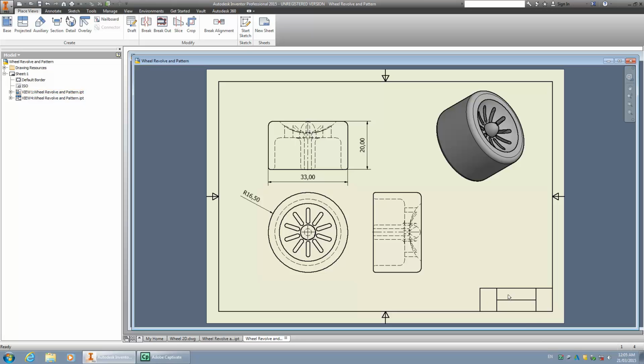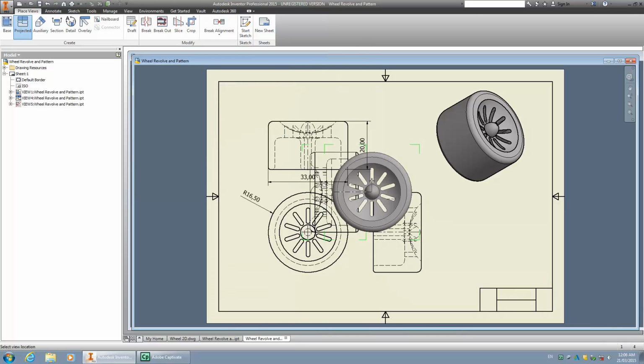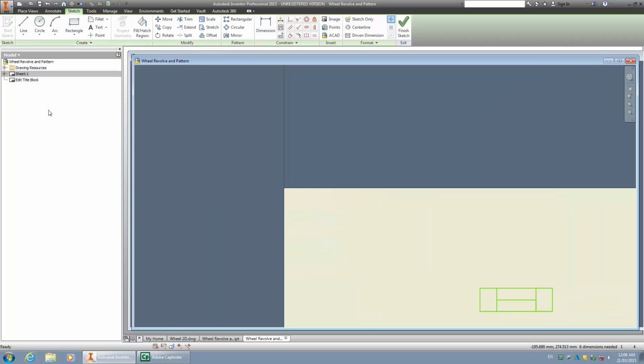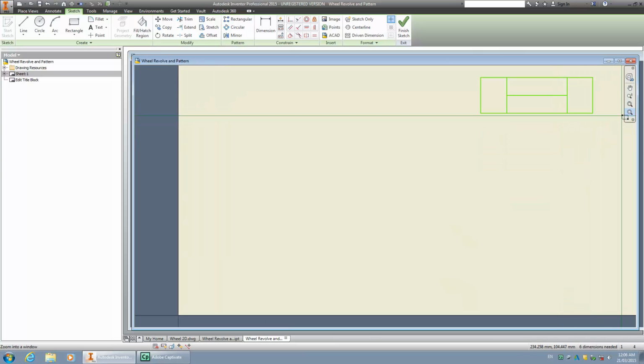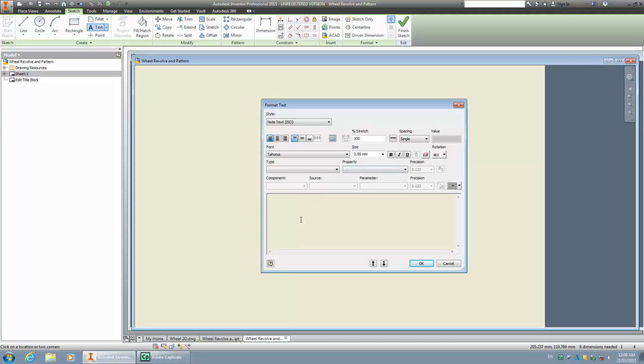You also ought to really fill in some information in this box over here that we've created, and you can do that quite easily as well. So again, right clicking, go to base view. Oops, we need to escape out of that. And Control Z if you get into problems with that. And we'll see if we can go, that's right, it's back to ISO, edit definition, and in our box, which will increase in size, drag it across a little bit. In our box we can use the text function, draw a text box in there. You've got your dialog box you can play with.